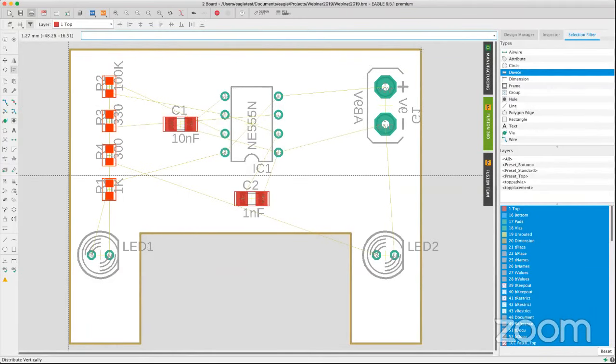The other thing I want to do is I would like to just make the attributes look a little nicer. So I'm going to use the move attribute option, and it gives us a whole bunch of really neat attribute repositioning right there. That one, attribute reposition.